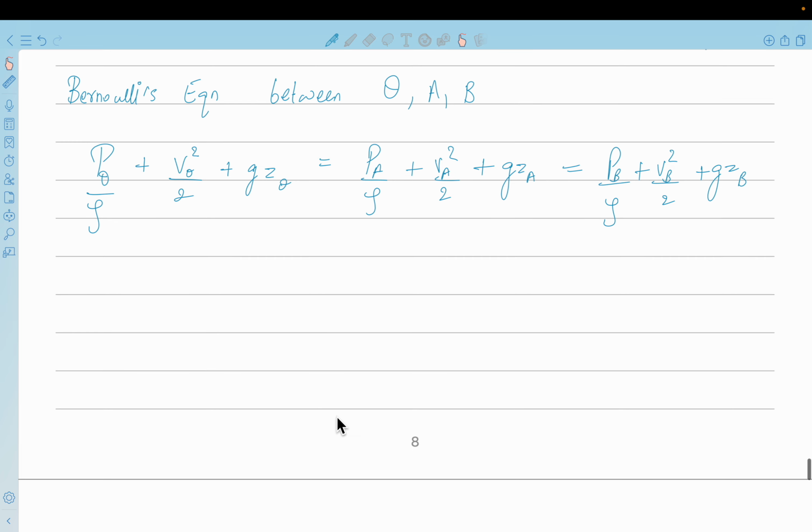Okay, so then let us find the pressure. Now, in the question it is given standard air, and this is usually information which is available. So there are standard air tables. We know the sea level conditions. If we know the sea level pressure, density, temperature, and we know the height is 1000 meters, then we can find the pressures. So P by P sea level at 1000 meters will be known to us.